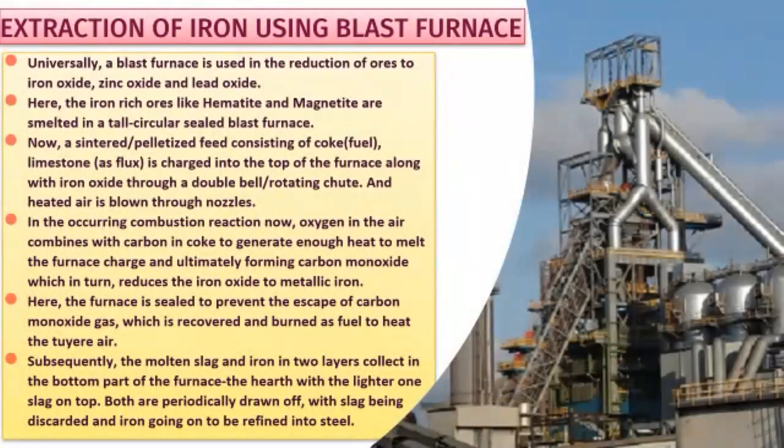Yes, that is the video description of the working of a blast furnace, where you have seen how smelting takes place. As already seen in the schematic diagram in the video description, the image on the right side of this slide is a blast furnace, and it is a universally used furnace in the process of reduction of iron ore, zinc oxide, and lead oxide. As already mentioned, a sintered or pelletized feed consisting of coke as fuel and limestone as flux is charged into the top of the furnace along with iron oxide through a double bell rotating chute, and hot air is blown through nozzles.